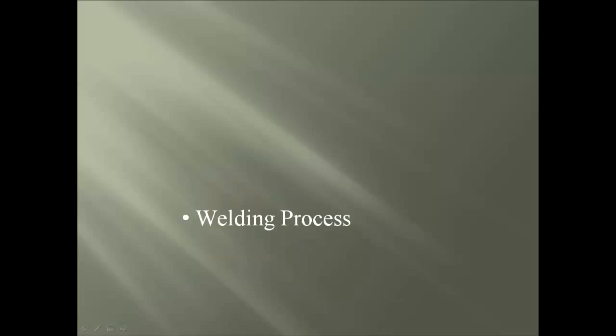We look at the welding processes for welding reinforcing steel, and as with plate or sheet steel, there are pre-approved processes that can be used without a qualification test, and those are shielded metal arc welding, gas metal arc welding, and flux core arc welding. And if at any time the manufacturer recommendation is not followed or another type of process needs to be used, that process must be approved by the engineer of record.